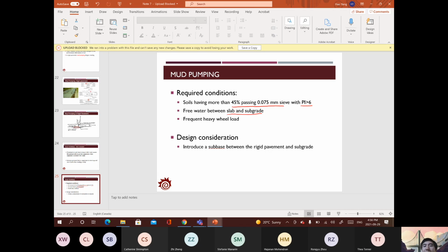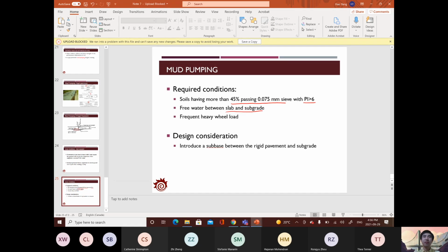And I highly recommend you review the impact analysis of the water contents on the physical properties of the soils, and also try to review the standard test for the compaction. This will be very beneficial for you to understand or to analyze the potential errors in the field and in the lab report.